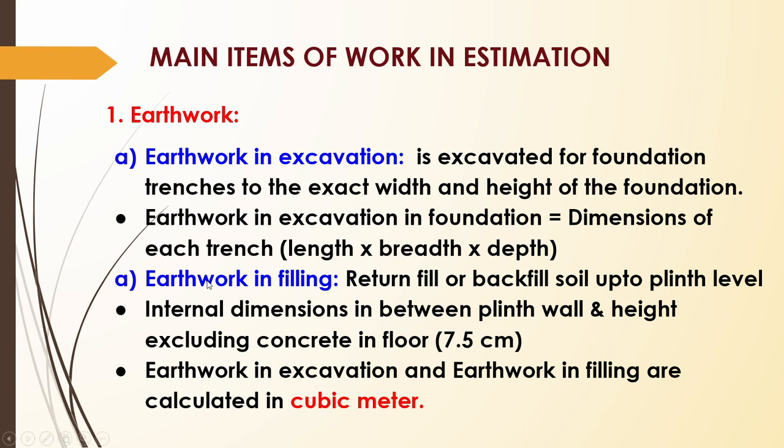So if you are doing the earthwork in filling, you will exclude the concrete in the floor, that is a 7.5 centimeter distance. Upside distance is reduced. For example, if you are making a foundation, after the foundation we will provide a flooring, right? Above the foundation we will provide a flooring. That flooring means we will provide some concrete, cement, and above that we will provide tiles. So that thickness is 7.5 centimeter. We will deduct that 7.5 centimeter. The remaining portions we will fill with soil.